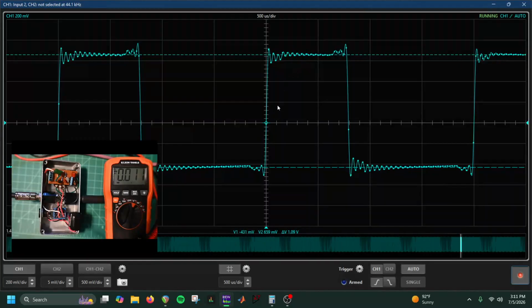And it's not this nice sinusoidal curve. It's very much a square wave with all these little harmonics over top of it. So we can see we're getting overall gain boost, but we're also clipping the waveform a lot. So this is where that term comes from, clipping. We're literally just clipping off the top of the waveform.